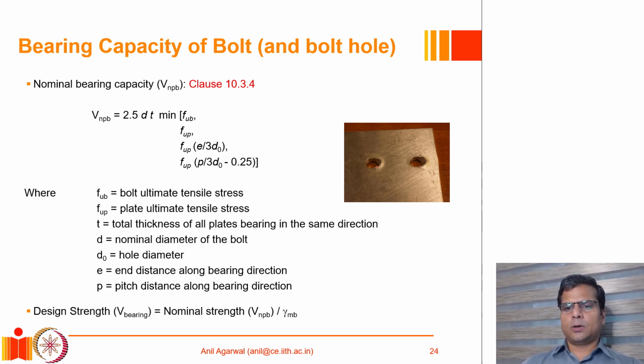So as we had seen, if a hole in a bolted joint is subjected to shearing stress, it actually translates into bearing stress concentration at the bolt hole surface, and then this portion of the plate, or the corresponding portion of the bolt, also can yield locally under that stress. In such a situation, the strength of the bolt or the bolt hole to resist this load has to be calculated, and that will form the other limit state.